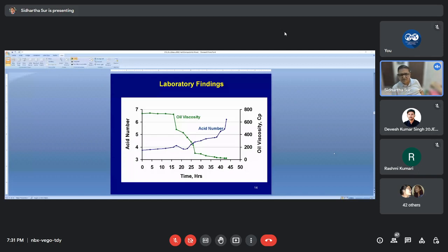It doesn't cut the chain. The oxygen gets added into the chain and forms organic acids. This is a very dangerous area for the in-situ combustion process, if insufficient oxygen is injected in a reservoir in the temperature range between 200 to 350.